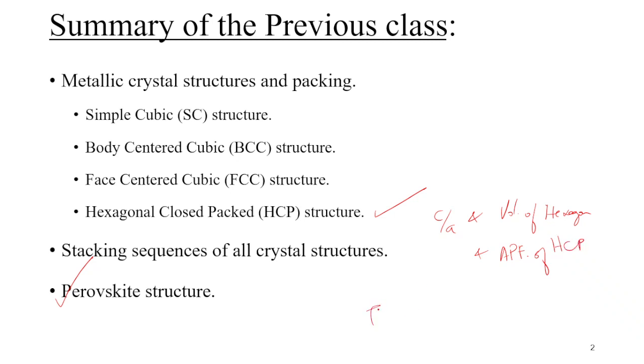Then we also discussed the theoretical packing factor of a material. There is the formula, right? The number of atoms times the atomic weight divided by what will come here? Any idea? Vc times Na, right?